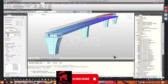We applied this load directly on beams because in the phase when they are activated, the slab is not active at all. The one relative to the workers in our case was very simple, because having the minimum value of the expression for calculating the load, we have a uniform distributed load of 0.75 kilonewton per square meter, distributed equally